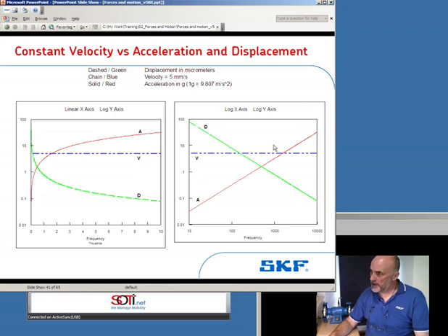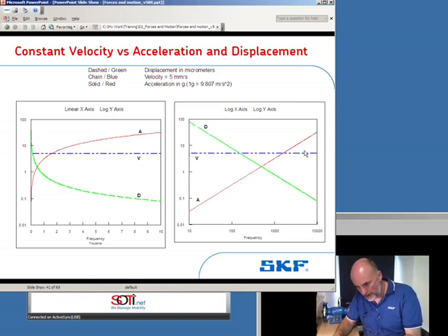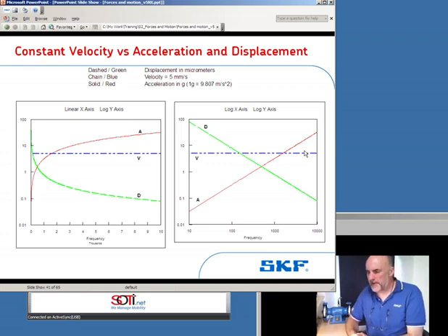The reason why velocity is used is that it's independent of machine speed. So if you said to me, come to America, I've got a machine that's running with 5 thousandths of an inch, what's that? That's 250 microns, 5 thou movement, I couldn't say whether that's good or bad unless I know the machine speed and the machine size.